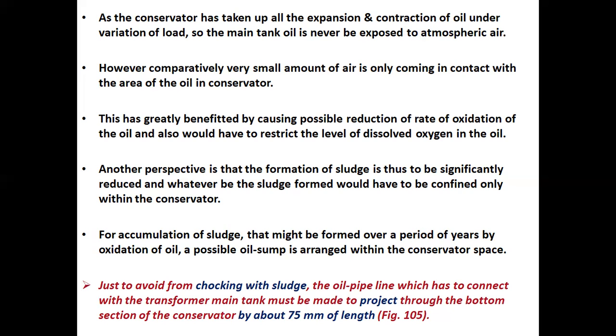A possible oil sump is arranged within the conservator space just to avoid choking with sludge. The oil pipeline which has to connect with the transformer main tank must be made to project through the bottom section of the conservator